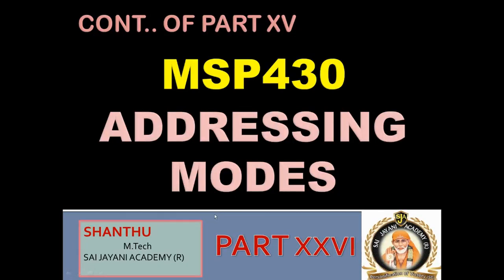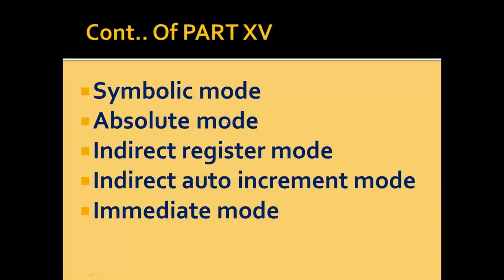Hello, welcome again. In continuation of part 25, MSP 430 addressing modes. Today we continue and we discuss the symbolic mode, absolute mode, indirect register mode, indirect auto increment mode, and immediate mode of addressing modes of the MSP 430 microcontroller.